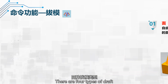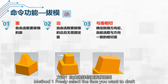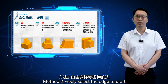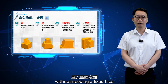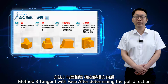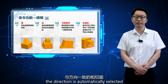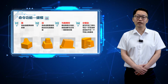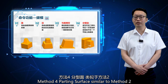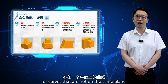There are 4 types of draft. Method 1. Freely select the face you want to draft. Method 2. Freely select the edge to draft without needing a fixed face. Method 3. Tangent with face. After determining the pull direction, the tangent face aligned with the direction is automatically selected. Method 4. Parting surface. Similar to Method 2, it allows for the continuous selection of curves that are not on the same plane.